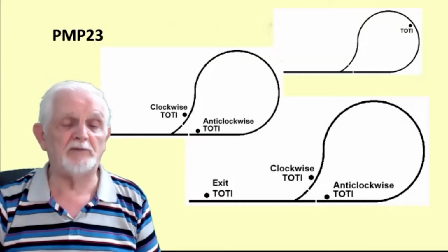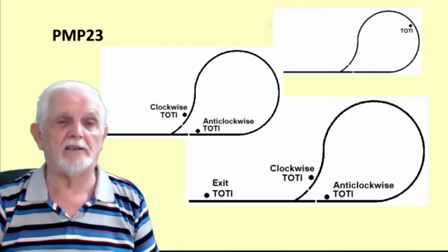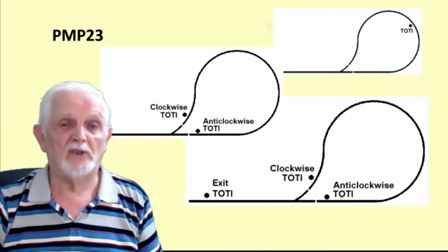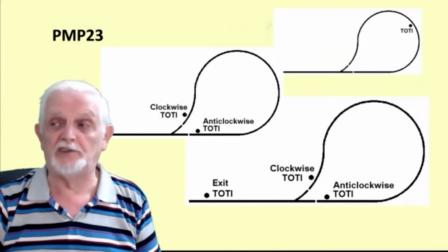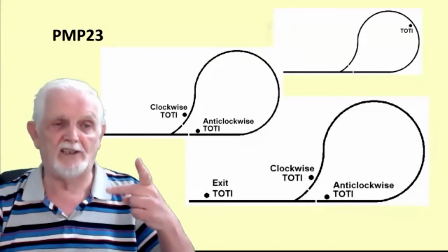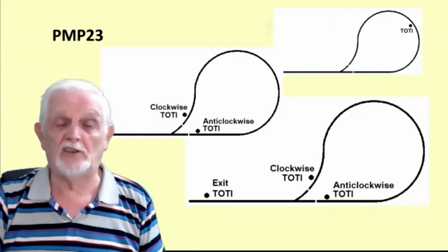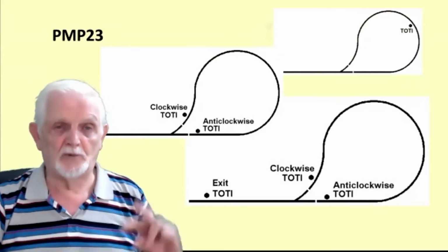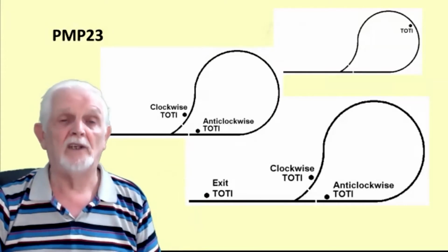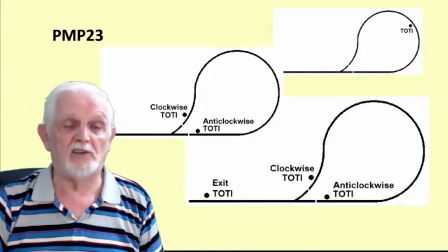For DCC, you still have to switch the track so we don't get shorts. But DCC being DCC, a locomotive decoder says go forward. It's not polarity conscious in that sense. It just keeps going forward. So as long as we switch the track polarity to avoid shorts at the point end, it'll carry on happily in either direction.